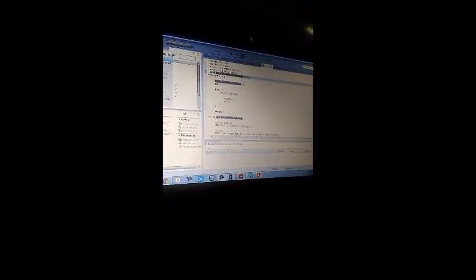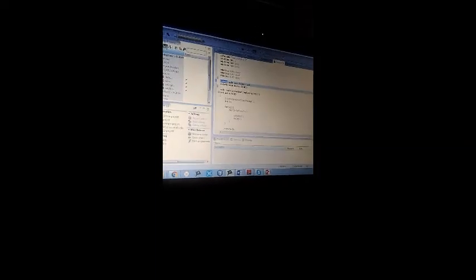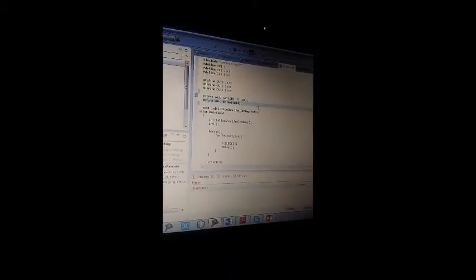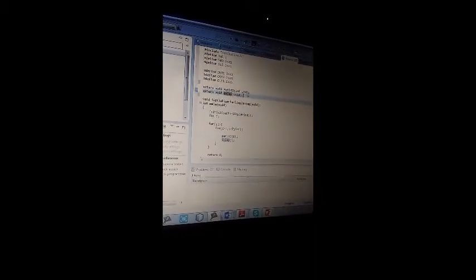I'm Kok, and I will proceed with the main.c file. So just now my friend Ho Jin Yong already explained the assembly code. Now I will explain how the C file works. In the C file we have two functions that have been declared by using the word extern. This is to link between the .c file and the .s file, which is the assembly file. Two of these functions are actually in the assembly file.